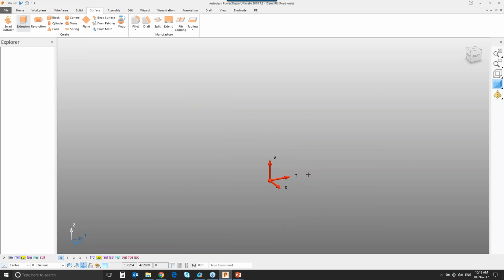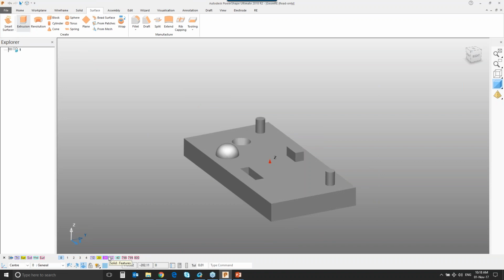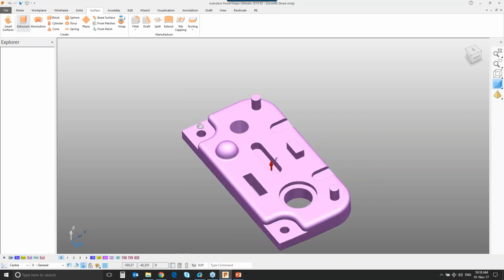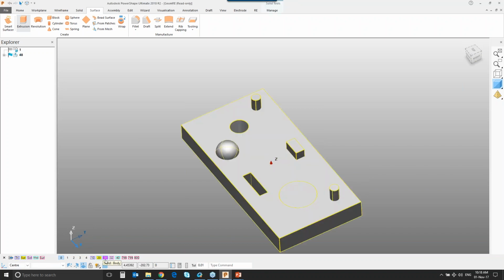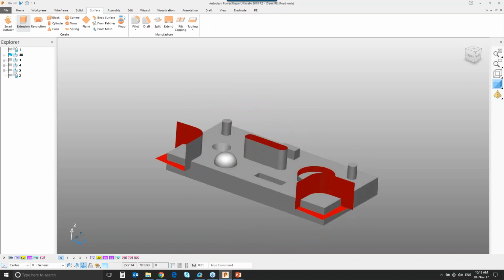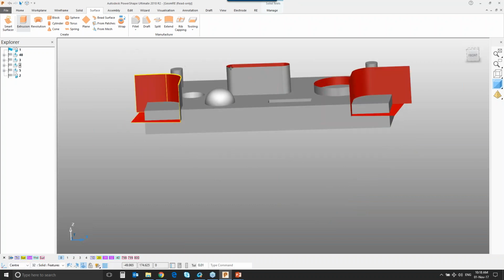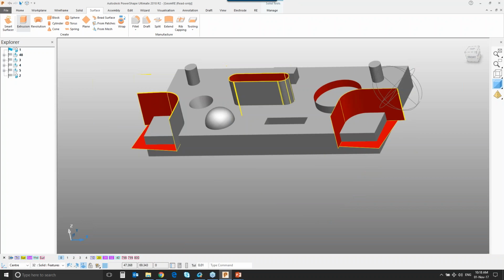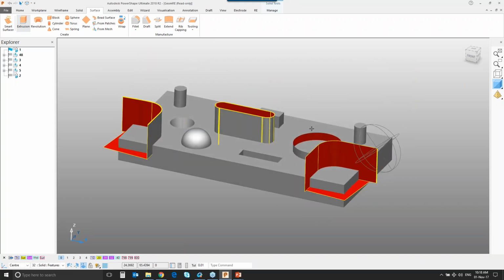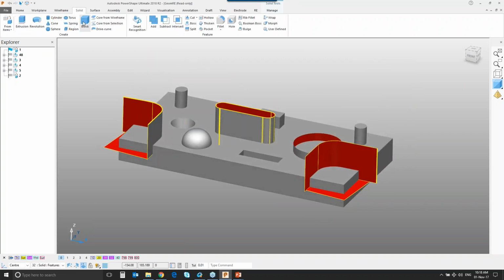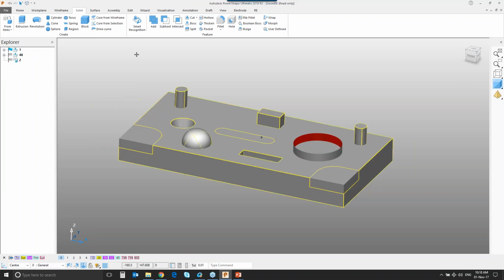And of course I could go and capture off with the segmenter tool the flat regions that were in that triangle model. So if I just draw that for you so you can see, I can use the segmenter to capture those two flat planes in the same way that we saw a moment ago. And what that leaves us then is key regions like this. Of course, I can then go and choose my main solid, which is this body here, and select these three solids that I've just created using the segmenter, the interactive trimming tool, to simply cut away the regions that are those corners.